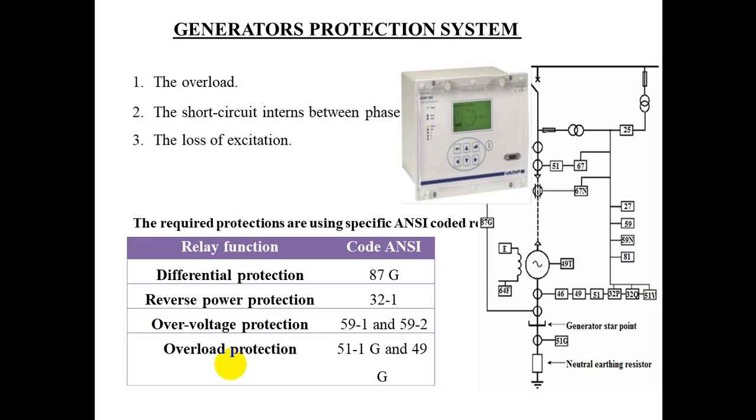The shaft axial expansion detector is basically similar to the equipment described for rotor distortion, except that the detector's magnets are fixed into the turbine casing.